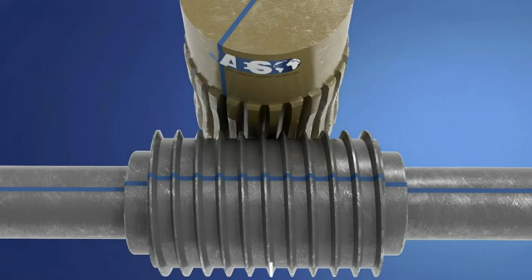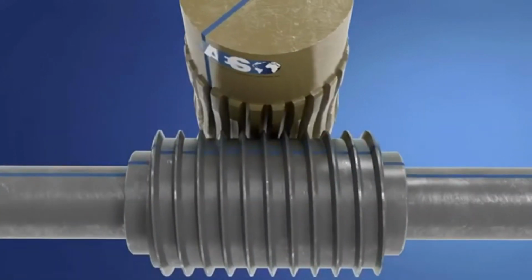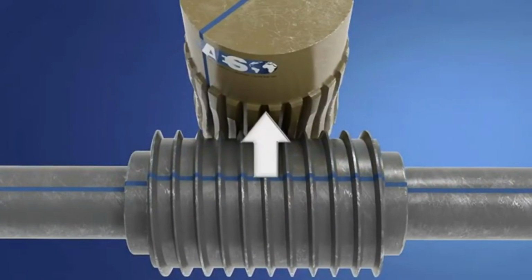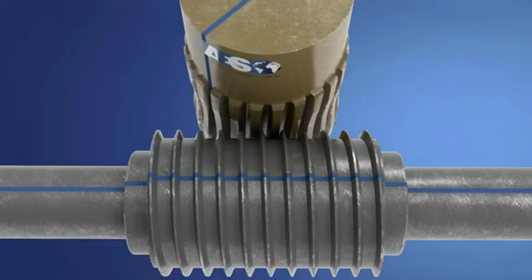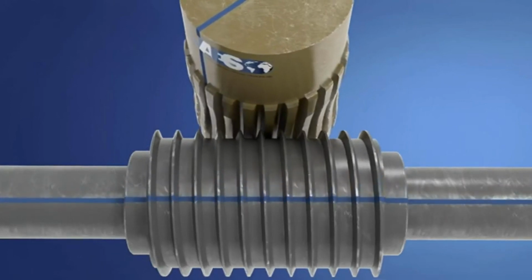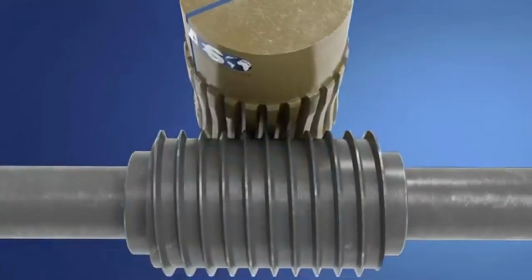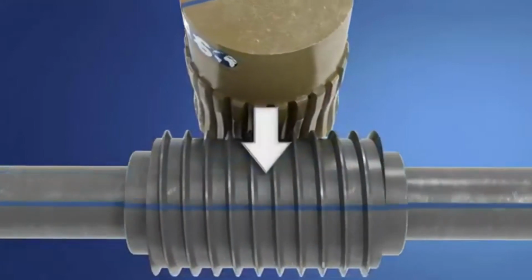The screw transmits the rotary motion to the worm gear. Usually, this motion can only be transmitted from the screw to the worm gear and not the other way around. However, there are some arrangements where the screw and the worm gear have such a thread angle that allows the worm gear to drive the screw.